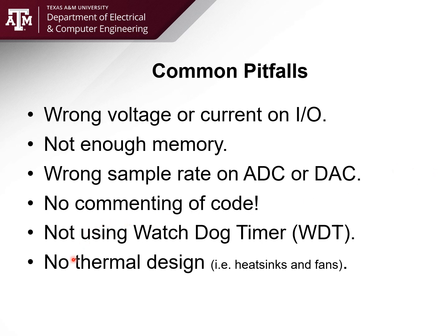Not commenting your code and not using a watchdog timer, that kind of goes without saying, and not planning any thermal design. Everything we're talking about, these microcontrollers do produce heat. They really do. Your Raspberry Pis do produce heat. So if you're planning a Raspberry Pi in a future project, make sure you buy the heatsink. By the way, they sell them for $40. It does not come with a heatsink.